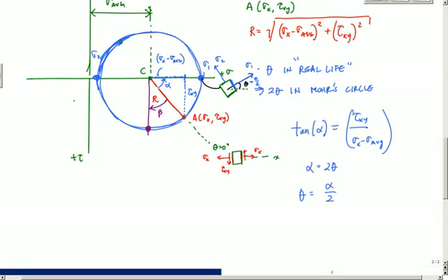And that angle is just, all I need to do is do this again right here. It's just 90 minus alpha, or beta: tangent beta is equal to, in this case, the opposite here, which would be sigma x minus sigma average, over the adjacent, tau xy. It's just a flip, or just 90 degrees, so beta is equal to 90 degrees minus alpha, because this is 90 right here. So, hey, great. Life is easy, right?